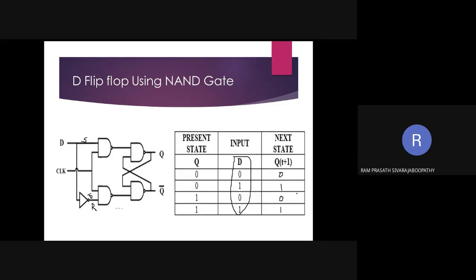Here there is no memory state. When the clock is enabled, whatever the input, it is available at the output. When the clock is disabled, it will get into the memory state. Okay, so kindly note it.